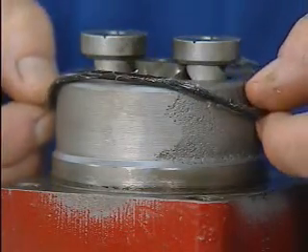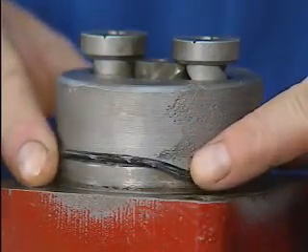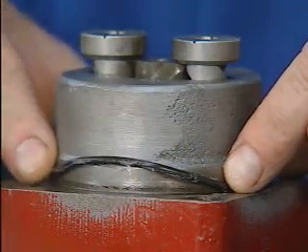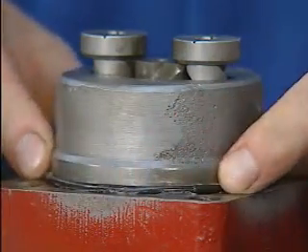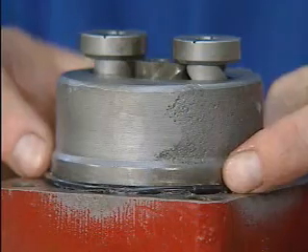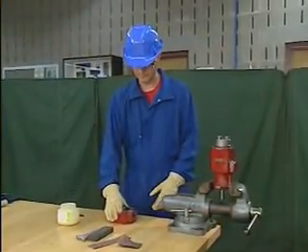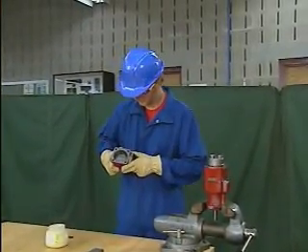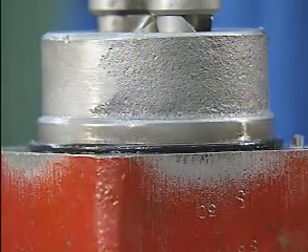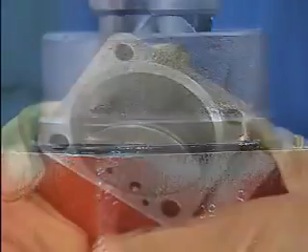Next, the mechanic places the O-ring onto the sleeve on the flange. The lubricated O-ring should fit easily but snugly into position, with just enough room to allow for compression. Once the O-ring is in place, the next step is to assemble the flanges. Care should be taken during this step to make sure that the O-ring is not pinched.